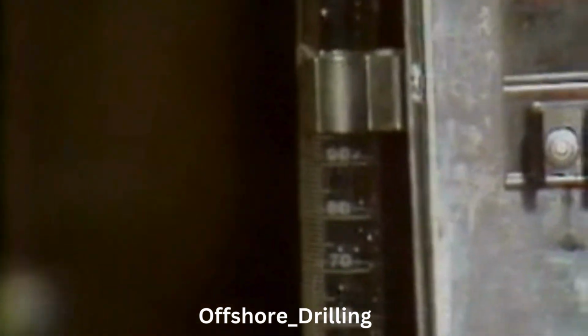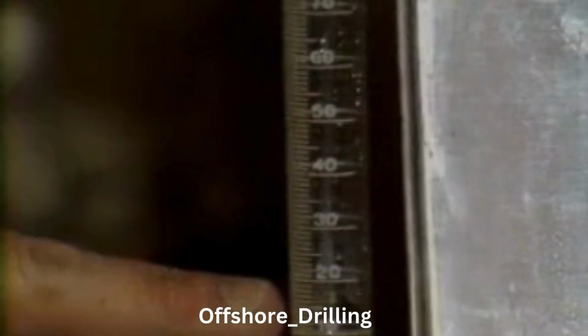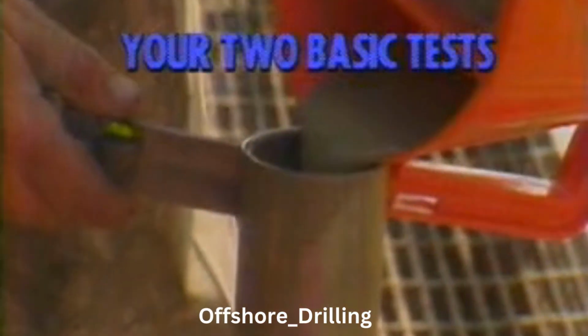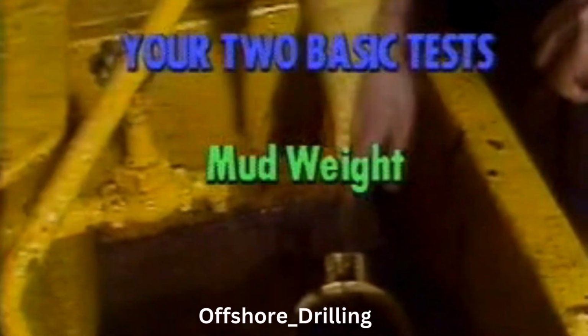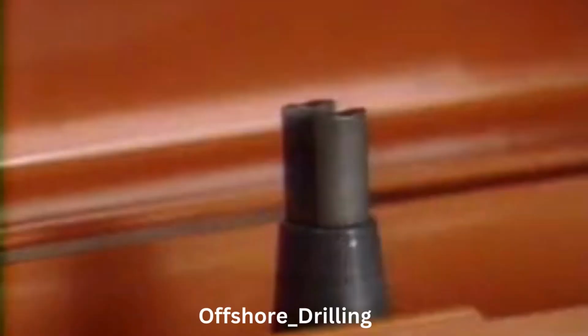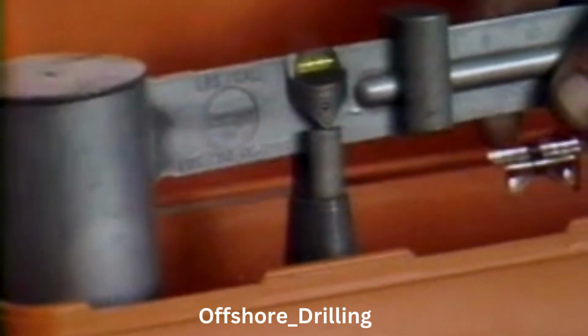Changes in the mud characteristics are what we're looking for, and to find them, a whole array of tests are performed. It starts with your two basic tests, mud weight and viscosity. We'll start with mud weight. When we talk about mud weight, we're really referring to mud density.